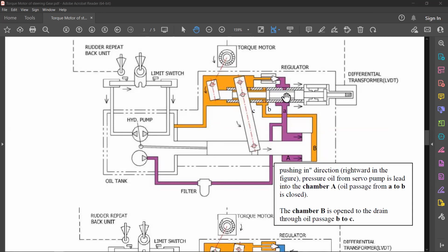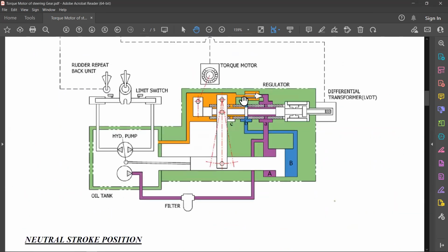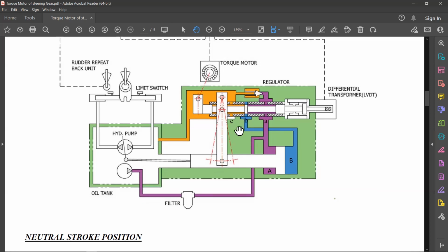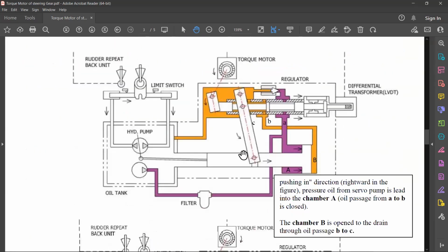So basically it is to de-energize both sides of the spool piston. Once the system is operated and is in a neutral position, for a few seconds this drain valve will open and will de-energize whatever is the higher side, either the A or B side, so that this spool piston does not always stay pressurized. Okay, this mechanism is provided inside it.